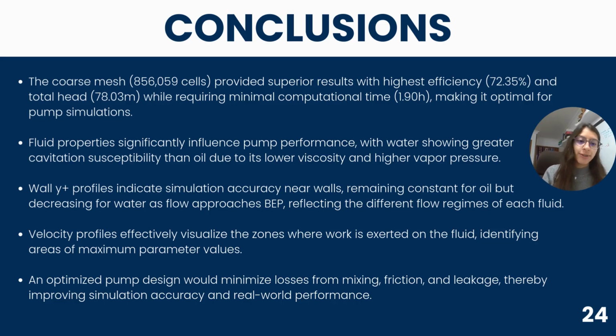Finally, due to the results obtained during the simulations, we can conclude that the coarse mesh provided superior results with higher efficiency and total head, while requiring minimal computational time, making it optimal for the pump simulation. Also, the fluid properties significantly influence pump performance, with water showing greater cavitation susceptibility than oil due to its lower viscosity and its higher vapor pressure.